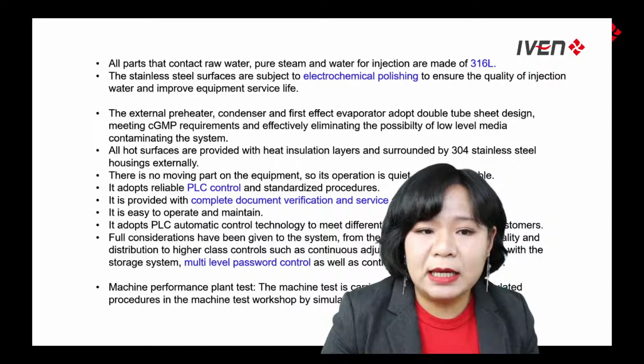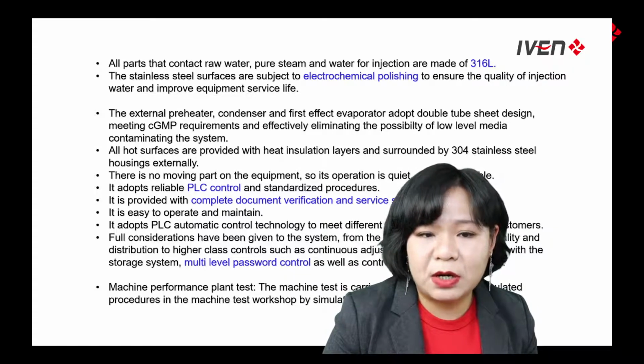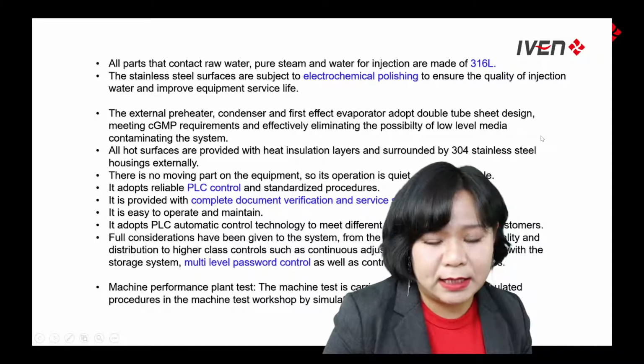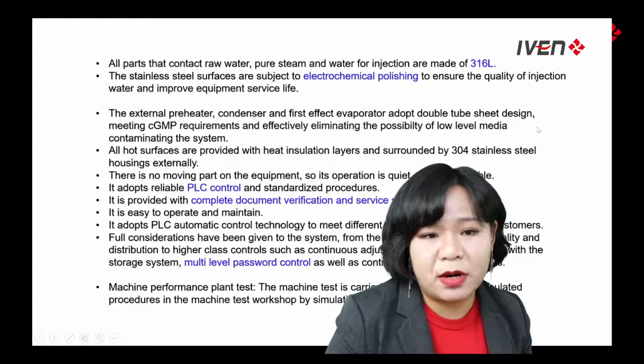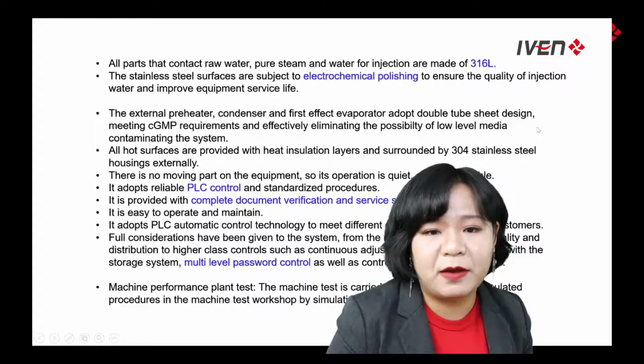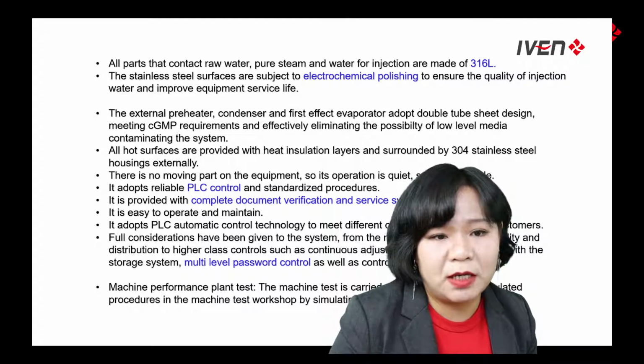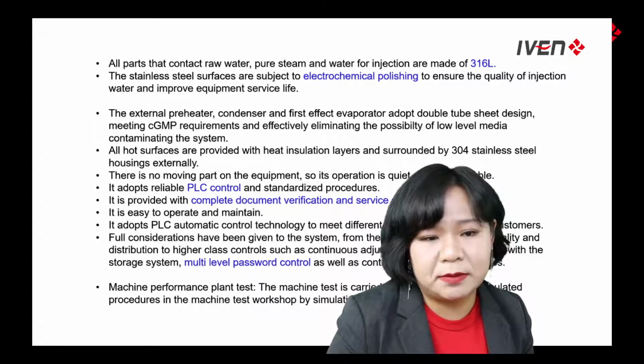The external preheater, condenser, and first effect adopt a double tube sheet design that meets current GMP requirements and effectively eliminates the possibility of cross-contamination in the system.